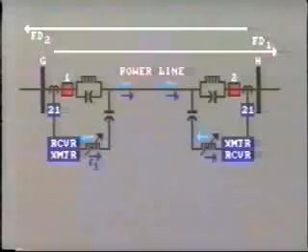A variation of the overreach scheme that we studied in the last segment uses frequency shift keying, FSK, of the transmitter instead of the on-off mode. This can be transmitted over PLC or by means of audio tones over a suitable channel. Let's look at the arrangement for PLC.